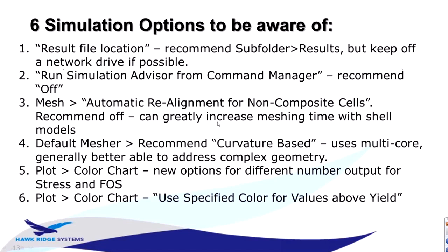It also means all those result files are put in a folder separate from the CAD files you're going to need. Okay? The only time I don't recommend doing that is if you're on a network drive. If you're on a network drive, you should always point the result files to a local fixed location. It'll run hundreds of times faster.